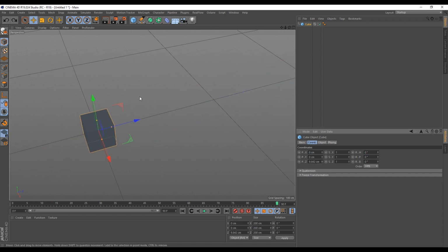Now to keyframing, there are 3 ways you can apply a keyframe here. You can apply it in the attribute panel here by clicking this circle, and when you click it, it becomes red this way. And once it becomes red, it means this property has been recorded at this particular frame in your timeline. So you see, you must always note where you are in your timeline. Once I take it out of frame 90, you see that our keyframe goes away, but once I take it back to 90, you see that that returns.